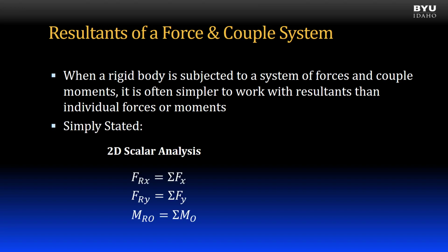So for two-dimensional problems, we will be summing the forces in the x and y direction and summing the moments about some particular point. For three-dimensional problems, we will do the same thing, sum forces and sum moments, except we will use vector notation.